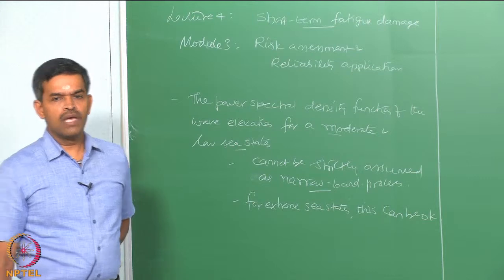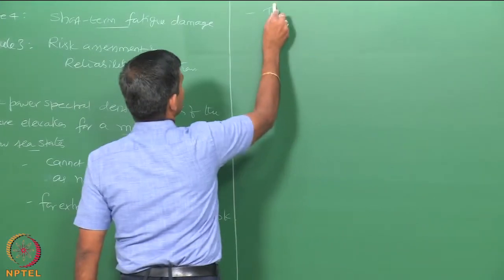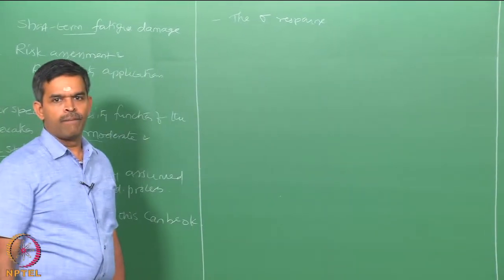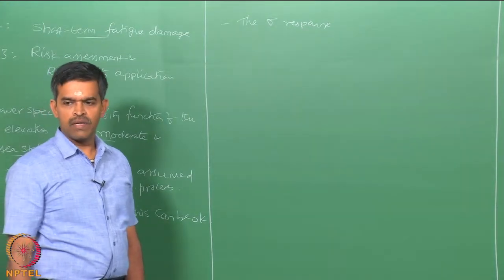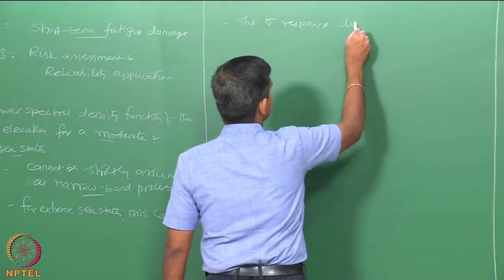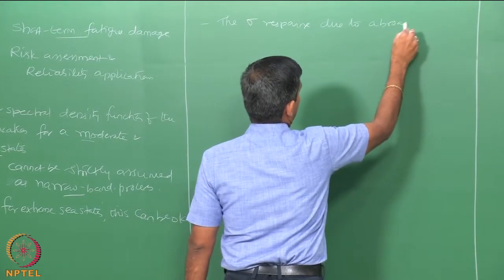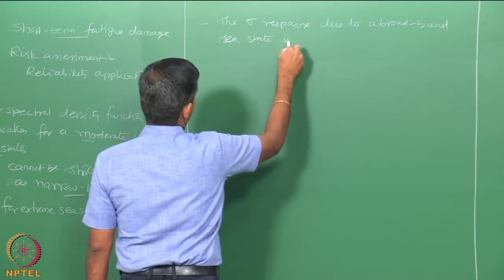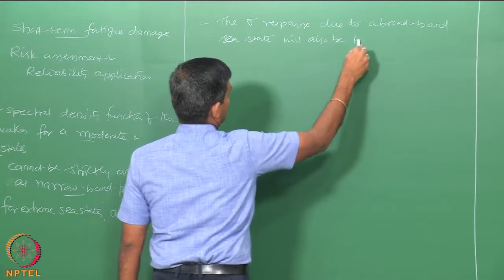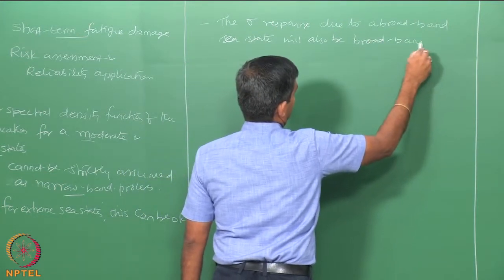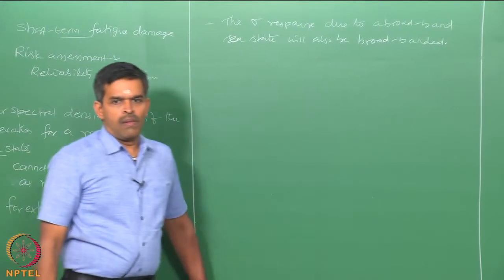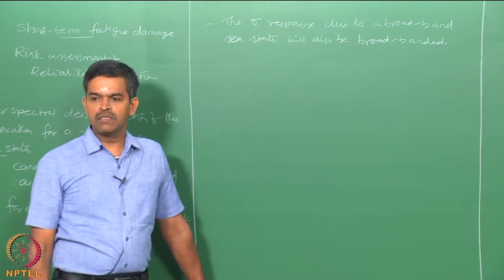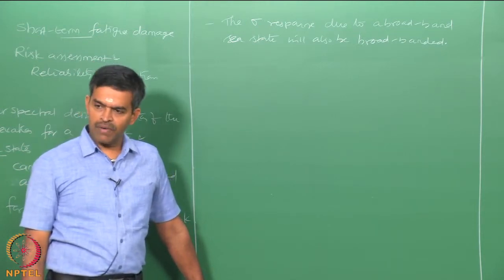Okay. Now, therefore, the stress response due to a broadband sea state will continue to remain as broadband, particularly when the dynamic response is not dominated by large amplification factors in any given natural modes of vibration.